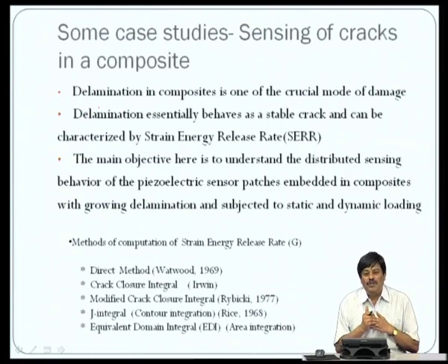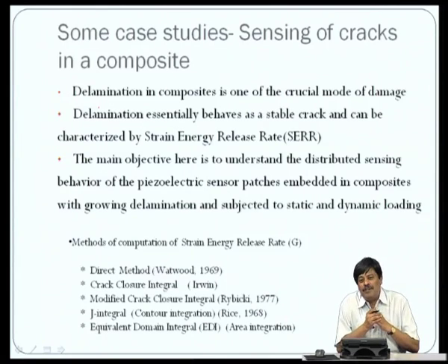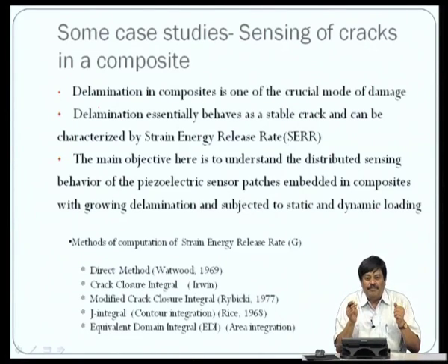So, is it possible to predict this delamination well in advance? That is the goal, and for this we can use the piezoelectric material. Here the delamination essentially behaves as a stable crack and can be characterized by what is known in fracture mechanics as the strain energy release rate. The main objective here is to understand the distributed sensing behavior of the piezoelectric sensor patches embedded in a composite with a growing delamination.